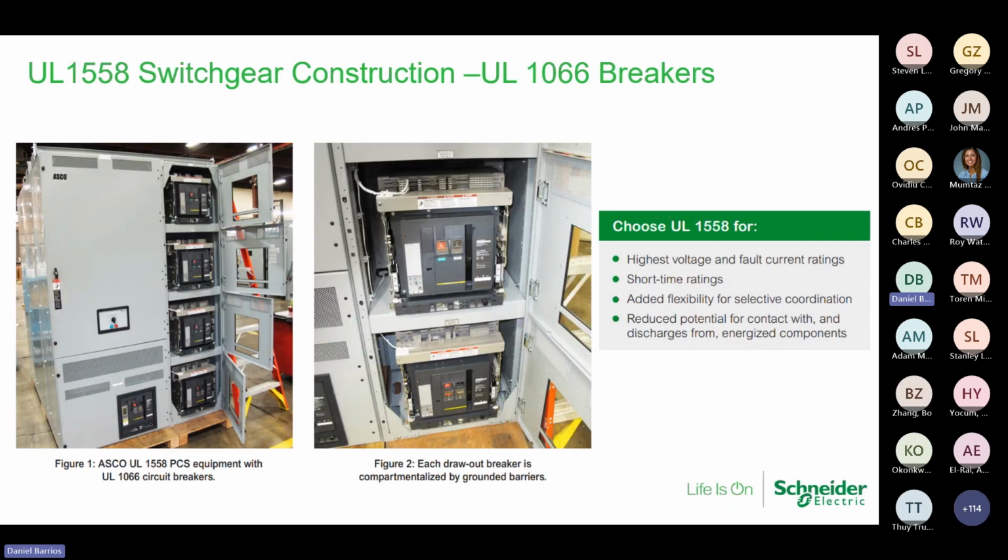As you go to UL 1558, highest voltage and fault current ratings, a short time rating can be considered. We can go with these up to 100,000 amps bracing.